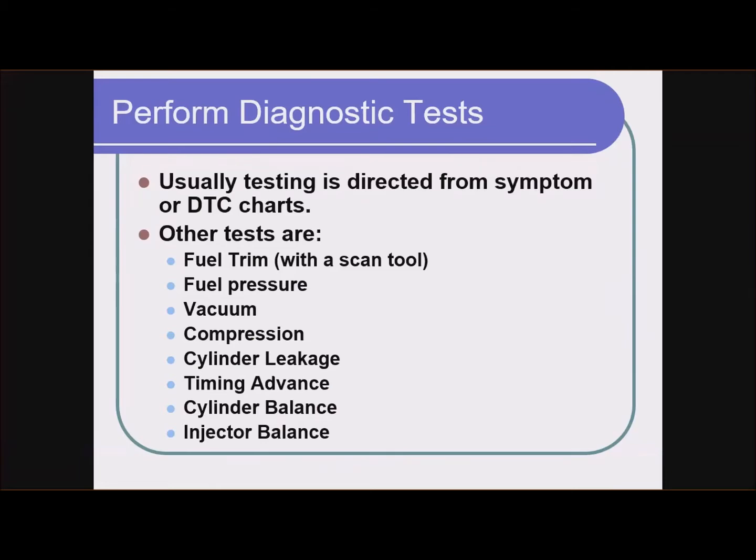And then the other thing you saw last lab video is when I pulled the hose off of the mass airflow sensor, the computer actually knew that there was a mass airflow sensor problem. It saw there was nothing, or not even a slightly realistic number coming from that sensor. So it chose to ignore that, and it chose not to use that in the air-fuel calculation. And so our fuel trim numbers didn't even move. They were still very small single digits because the car was using other sensors to calculate the correct fuel delivery.